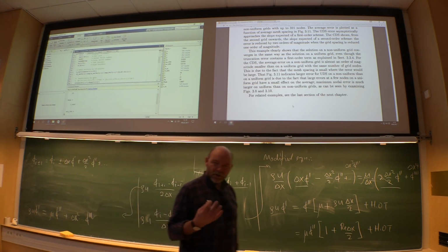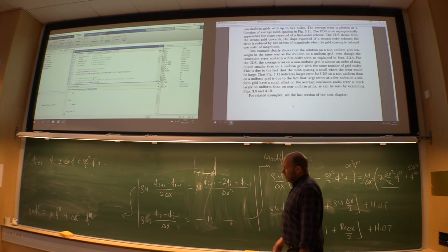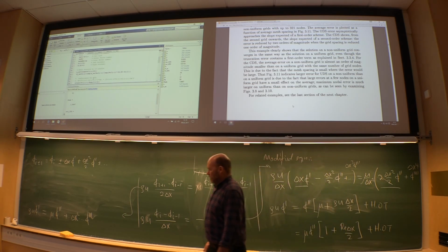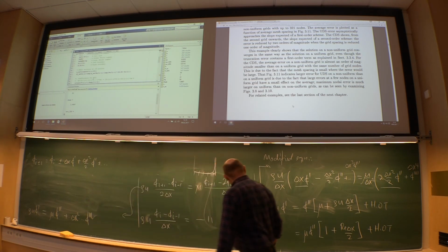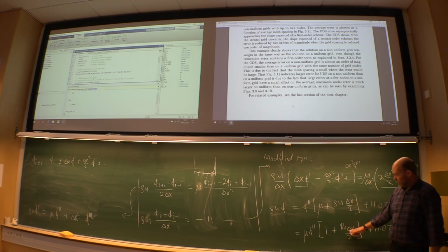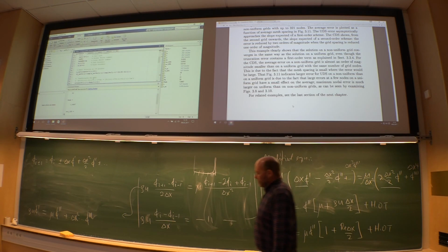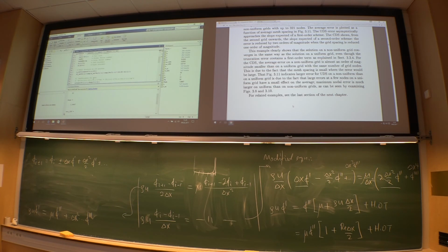You don't get any additional double derivatives into the equation system. So he doesn't include any more diffusion. He includes a truncation error of order delta x square. First order upwind, of course the truncation error is of order delta x. So central scheme, yes, much better, but sadly much more unstable. Hard to find correct solutions.